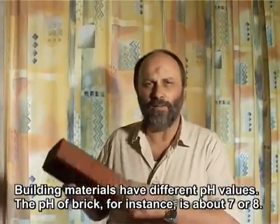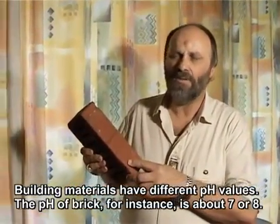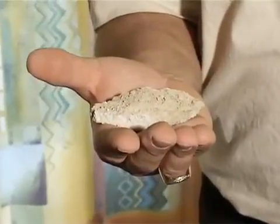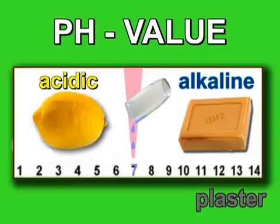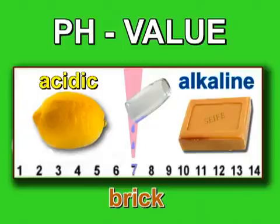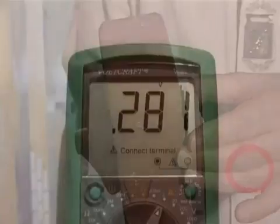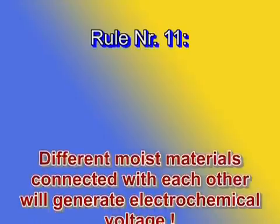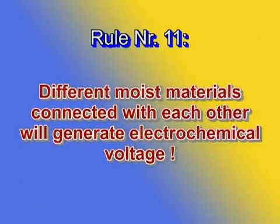Building materials have different pH values. The pH of brick, for instance, is about 7 or 8. Cement-based plaster has a pH of 13 to 14, thus it is highly alkaline. When materials of different pHs come together, as for instance brick and cement-based plaster, you will obtain a measurable electrochemical voltage between these materials. Rule number 11. Different moist materials connected with each other will generate electrochemical voltage.